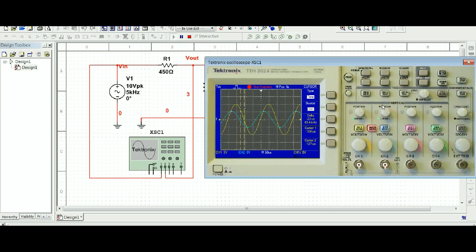So, looking at my delta on this, what I see is that the delta is negative 23 microseconds. And doing a calculation on that, it's negative 23, and I really don't need to worry about the sign, the reason being it depends on what cursor I put first and second as to whether it's negative or positive. But what I know from this is my output waveform, blue, is leading my source voltage, and I'm going to use that information and not worry about the sign of this. So I have 23 microseconds difference, and now I'm going to have to divide that by the period of the waveform.